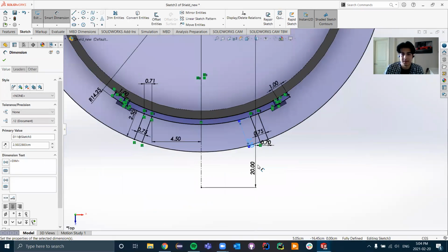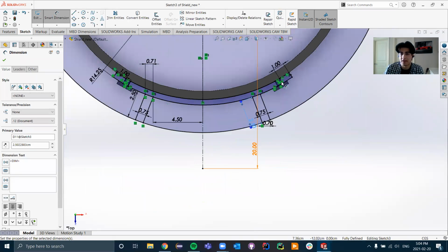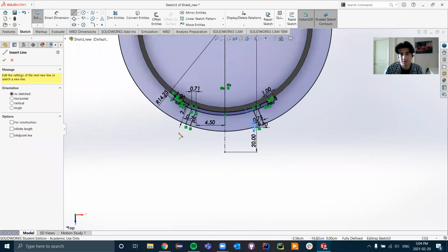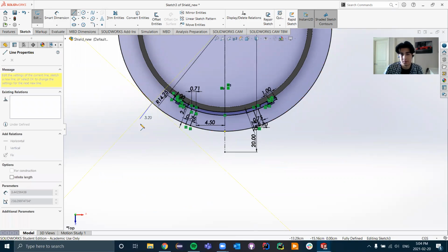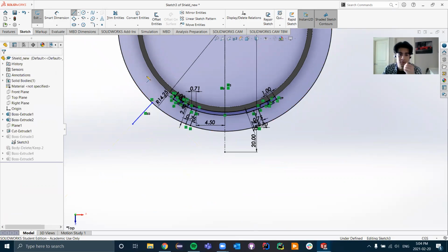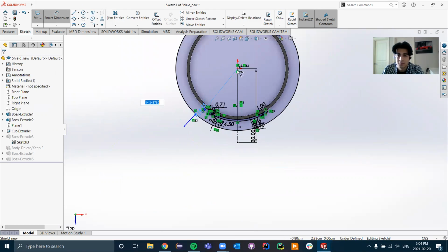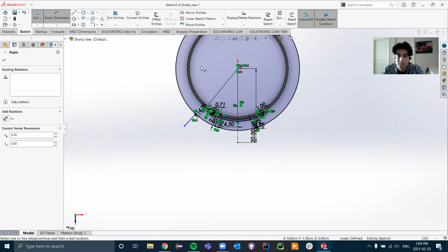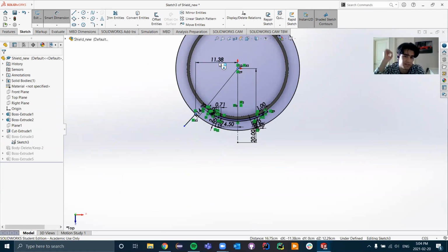All right, and now we can go to our second step, which is essentially creating the edges of this component. And you'll see what I mean quite soon. So say if we go and create another perpendicular component lines as such, there we go, and give it a dimension, oh, whoops. So we'll give it a smart dimension of, if I zoom out here, base to the origin, we'll say approximately 11 centimeters, why not?